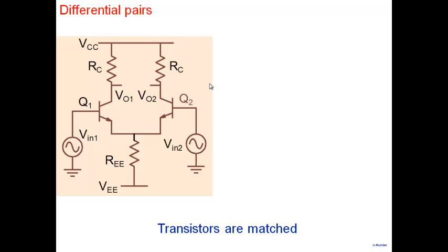All right, so we've seen that the differential amplifier is a natural solution to building an amplifier on an IC. Here is an amplifier which I'm able to bias through this negative supply voltage and RE, and I'm able to apply my input also without requiring any coupling capacitors. No coupling capacitors anywhere in the circuit, no external capacitors anywhere in the circuit, and therefore this differential amplifier can be easily and efficiently built on a piece of silicon. The other important property is that it amplifies the differential mode signal and rejects the common mode signal. The next thing that we have to do is a more detailed analysis of this particular amplifier.